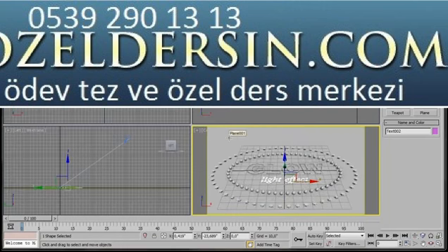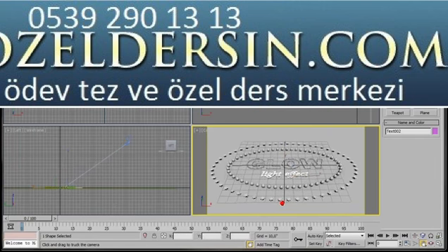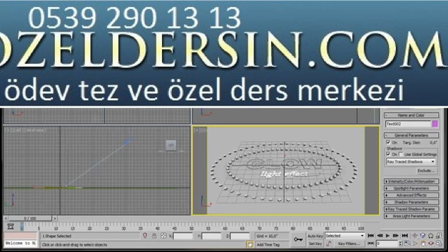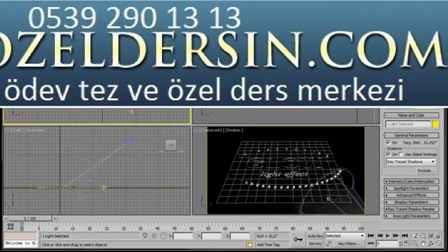We can grab the pan tool to move the scene in our camera viewport a minute. There we are, something like that. Let's add a light now. So we'll go up to the Create panel, Lights. Behind Photometric, we'll find the standard lights. Now we're going to select a mental ray area spot. Let's drag this out here in the top viewport.